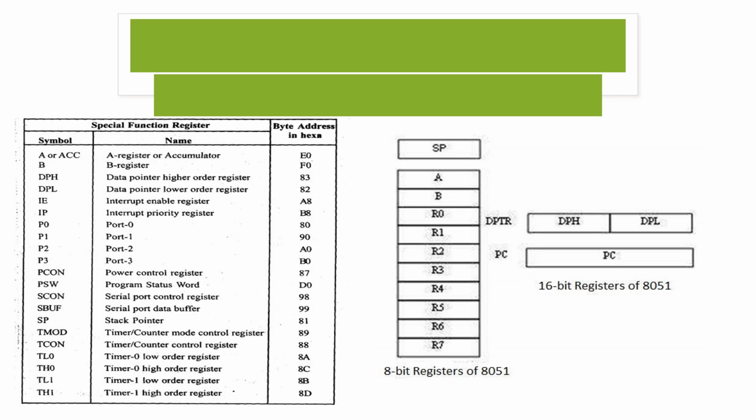And serial communication registers, here you can see you have SCON and SBUF, that is serial port control register and serial port data buffer. So these are going to facilitate the serial communication with the external devices. And there are input output ports which we saw, right? Port 0 to port 3, P0, P1, P2, P3. These all control the data direction of each of the pins in the corresponding input output ports.